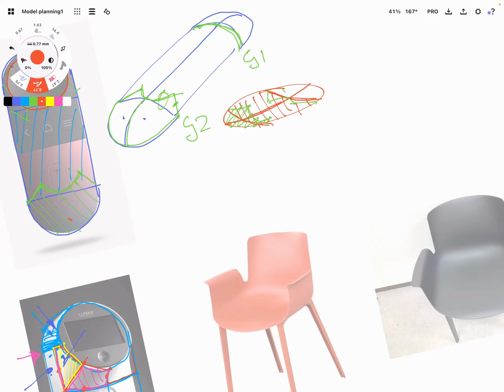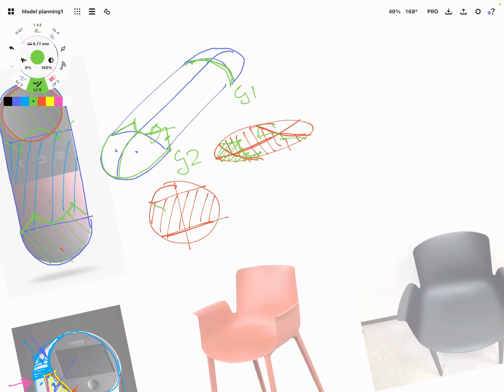So in plan view that would look like circle, center line, that's your first surface, and then your second is you trim that out and build your second surface in there, which seems like a lot of work, especially if that dimple's very shallow.